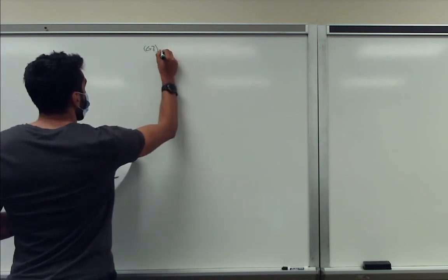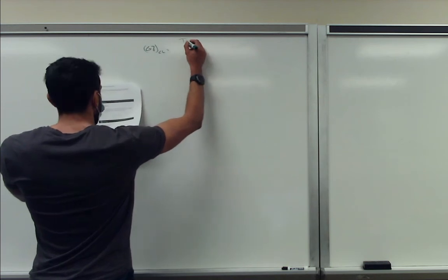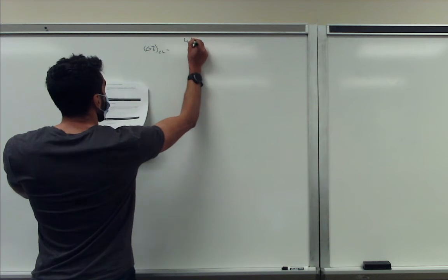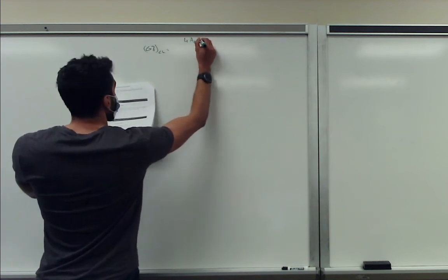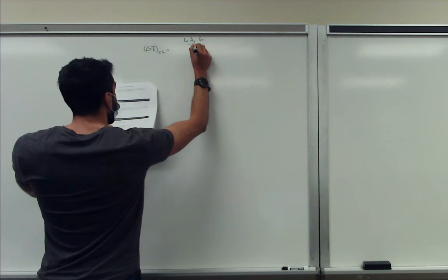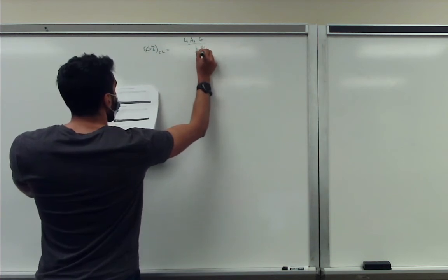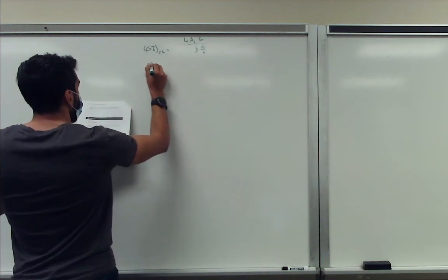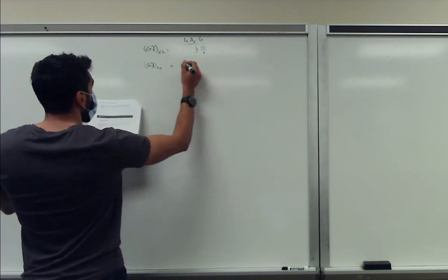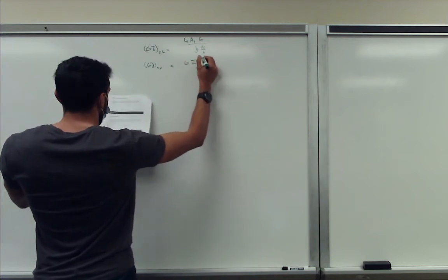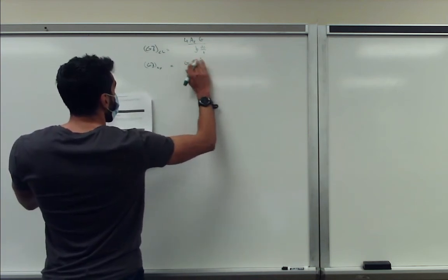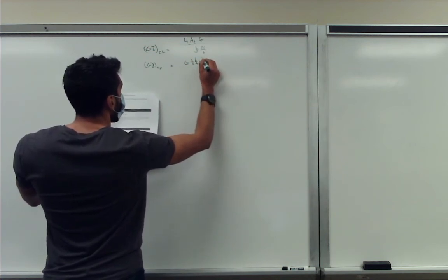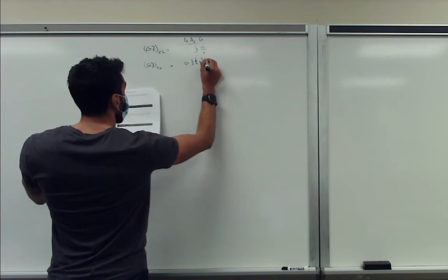For the closed section, we use our equation of 4 times the area squared times G over the integral of ds over t. And for the open section, we use G times the summation of one third of the integral of t cubed ds.